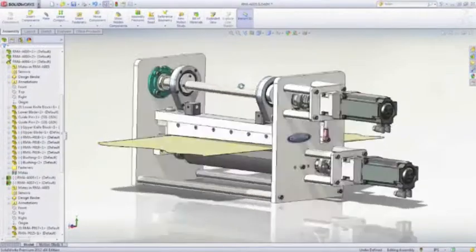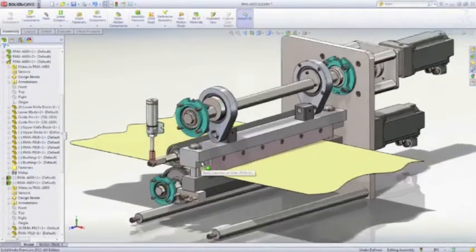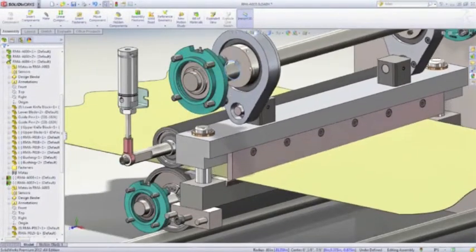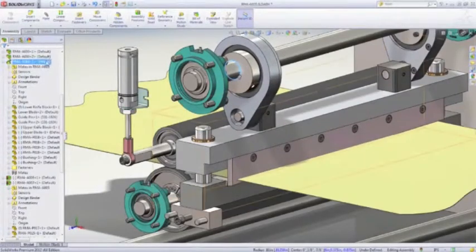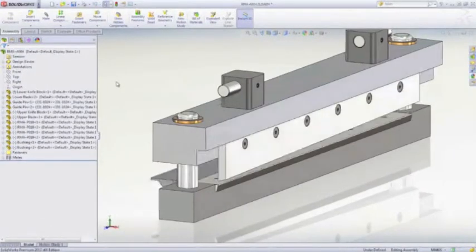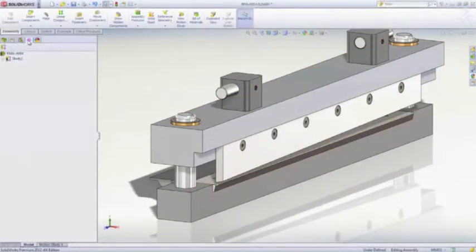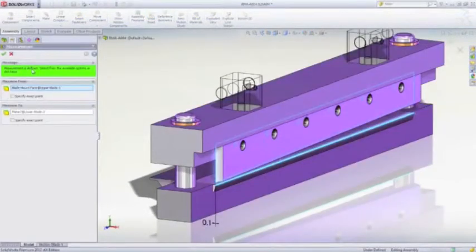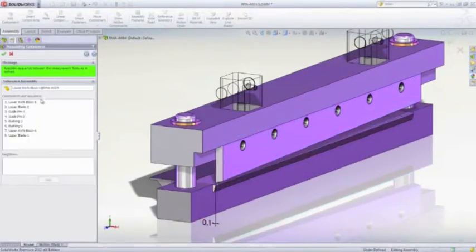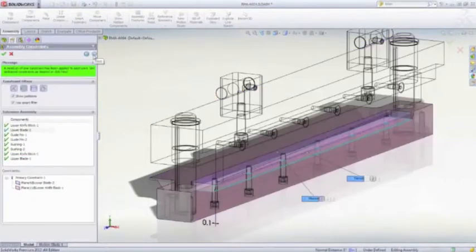Tolerance Stackup Analysis is vital to mechanical fit and function, and SolidWorks TolAnalyst makes this easy. Leveraging the individual part tolerances, TolAnalyst can be used to measure the gap between these 2 blades in this sheeter assembly. First, establish a measurement between 2 features. Then, identify the assembly sequence. Next, define how each part is placed or constrained in the assembly.